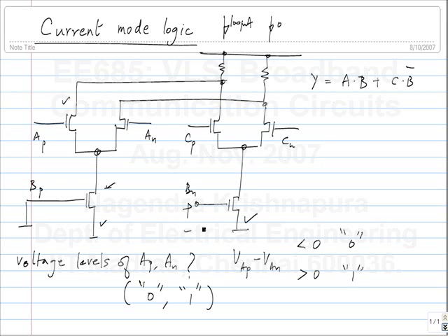What's the consequence of that? The swings will be different. You assume some output swing for this one, so that will change, and you may not be able to drive the next stage very well. That is one issue. Not to mention, the biggest advantage of digital circuitry is noise margin, right?